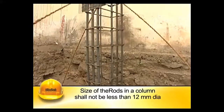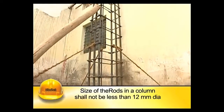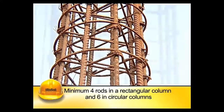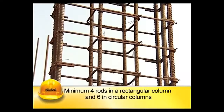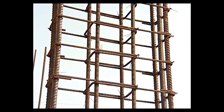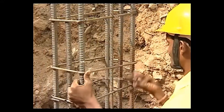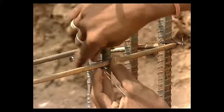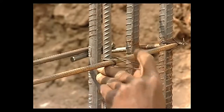The size of the rods in a column shall not be less than 12 mm dia and there should be a minimum of 4 rods in a rectangular column and 6 in circular columns. The horizontal distance between vertical rods in a column shall not exceed 300 mm. Ensure that the column reinforcement cage is held in vertical position till concreting of foundation.